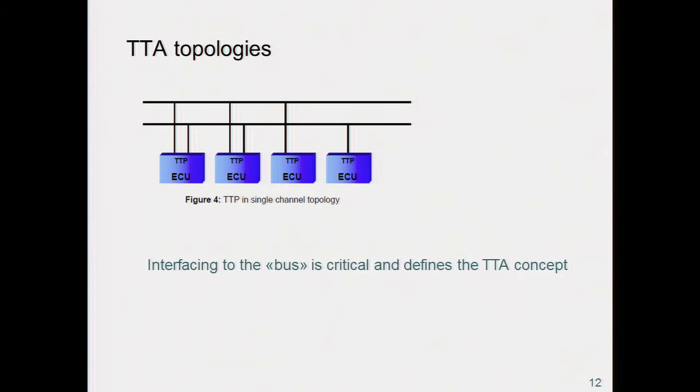And this is exactly the same as what you have in synchronous circuits. What happens when you have a block, right? You compute, and then you write onto a register. And when the clock comes in, you shift this information to another register, right? And then this register is free to have another writing, and this register is ready to be read by the rest of the thing. So we have to do something exactly the same, right? We have to try to do the same in a distributed environment.